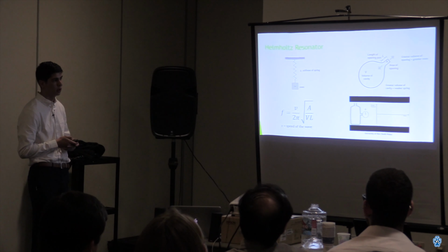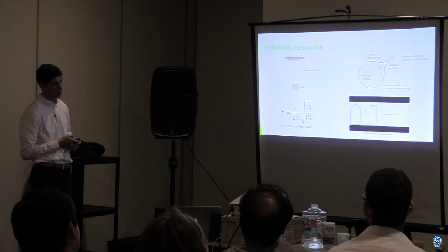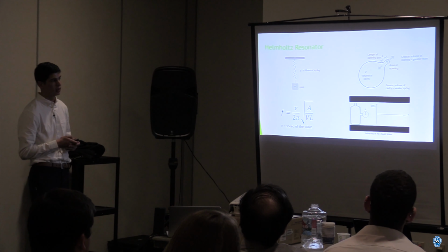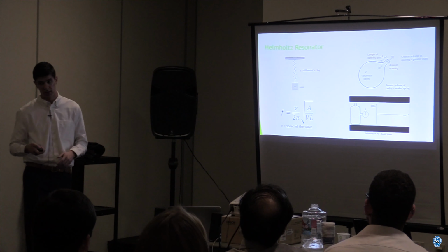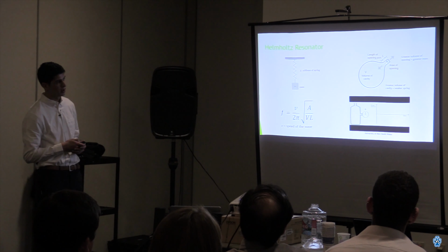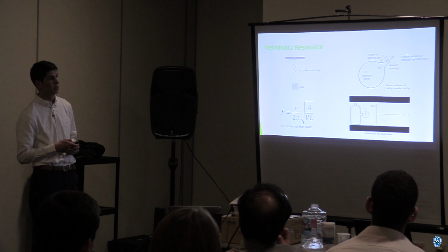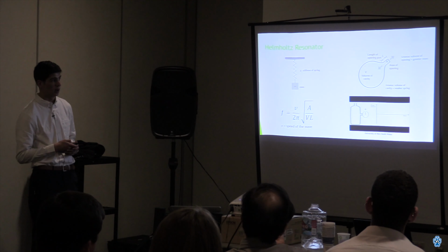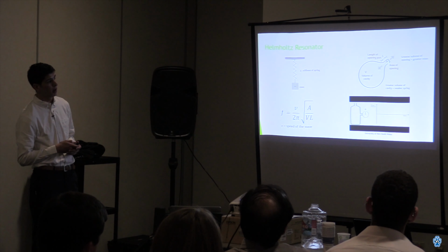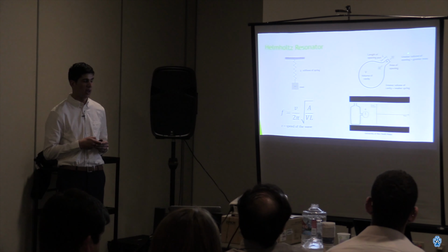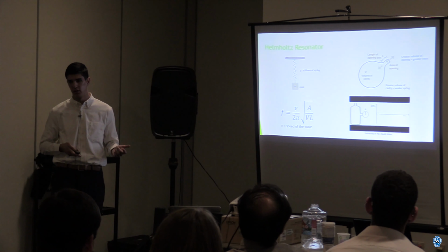So this works very similar. Right here is analogous to the mass on the spring, and the volume right here is the spring itself, the stiffness of it. As air gets directed into the cavity, it's going to compress, and then it's going to want to go back to equilibrium, so it pushes back out, and then there's an oscillation in the air. My port, my neck right there, is my helix design, so that every time it goes in and out, it goes through the helix and it loses energy that way.